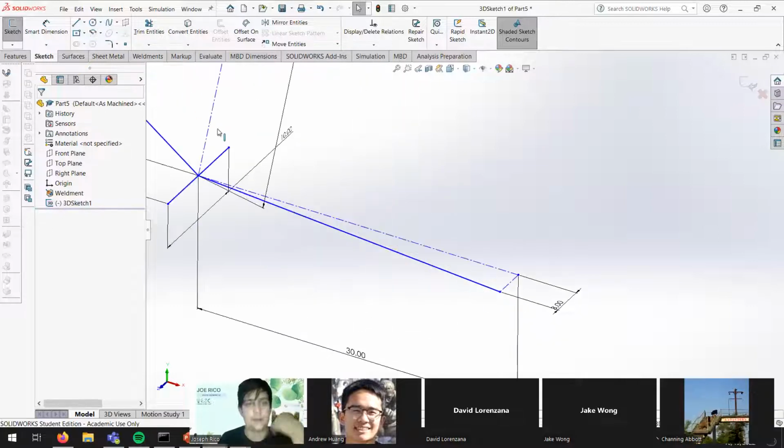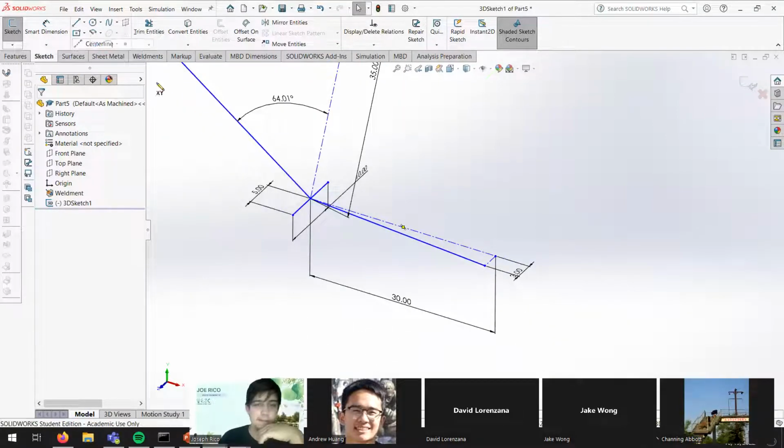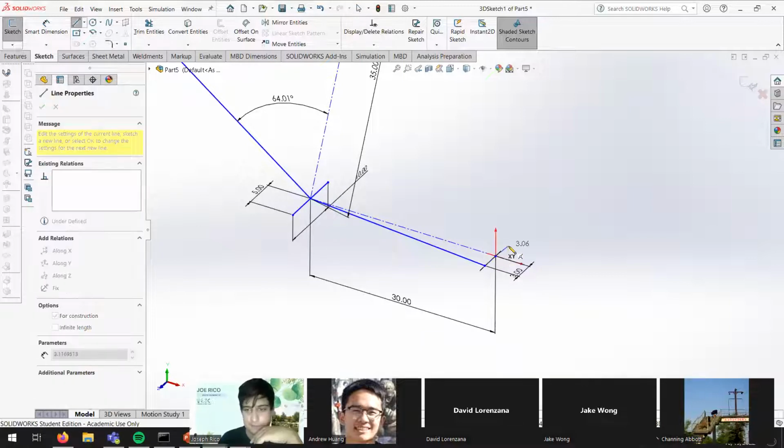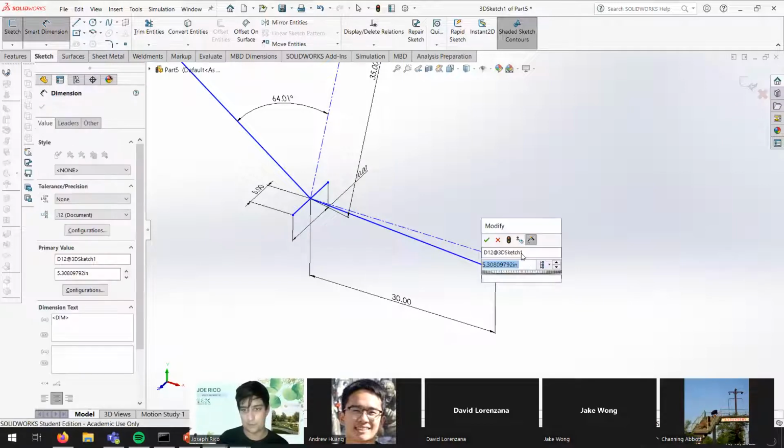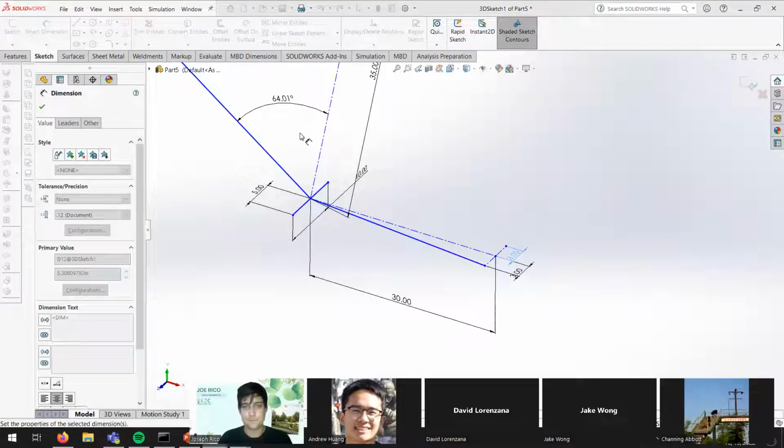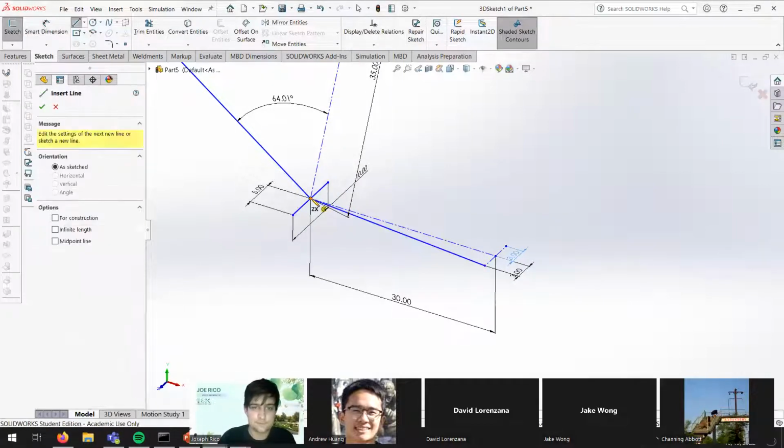And I don't get why I didn't want a mirror, but that's SolidWorks for you. Sometimes it just gets unhappy. So we're going to go back to what we were doing and just drop this line 3 inches, exactly the same. I think mirroring literally probably takes longer in this scenario, but I just wanted to show that was possible.